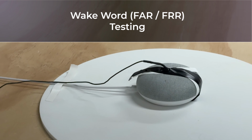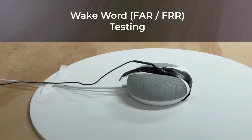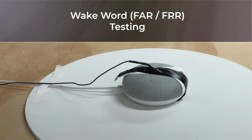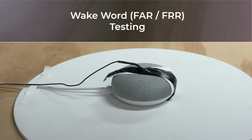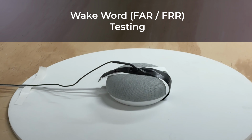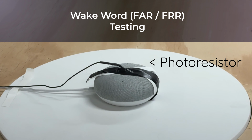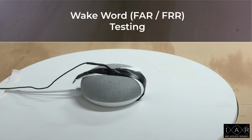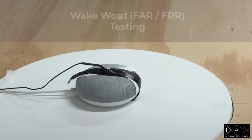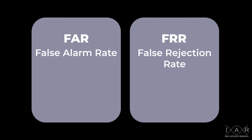This video describes an automated way to collect wake word performance on third-party devices for which you may not have programmatic access. This method works as long as there's an activation light to indicate a successful wake, as a photoresistor is used to capture the voltage difference between light and dark output over the LED. The output metrics collected are false alarm rate, FAR, and false rejection rate, FRR.